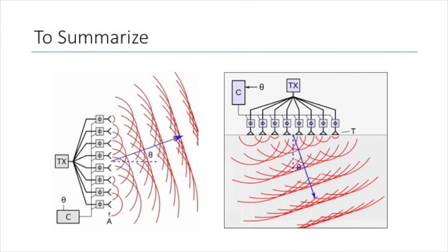To summarize, antenna arrays are a combination of two or more antennas that have an increased performance over a single antenna by producing a higher antenna gain and providing the capability of a steerable and directive signal. These characteristics allow us to utilize antenna arrays in every technology, such as satellite communications, wireless communications, and much more.